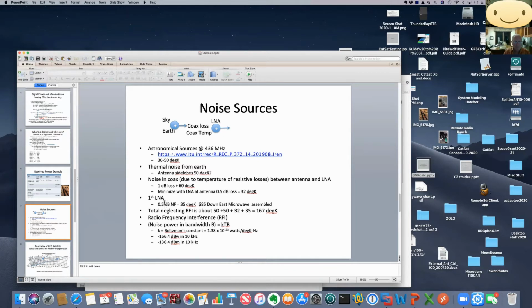If, on the other hand, we're between my operating position and my antenna, maybe it's typically 100 feet, or 150 feet, 200 feet, and let me go get some typical cable, RG58, nice 50 ohm cable, small and flexible. It may well have 15 or 20 dB loss. The signal gets attenuated and the cable adds noise, and you don't hear much of anything.